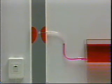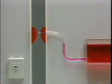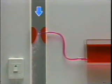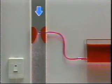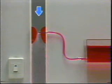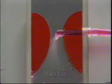Now, let's narrow down the mouth of the tube to speed up the airflow and see what happens when we try it again. As you can see, liquid is atomized, that is, changed into a mist that can be blown out through the pipe. This is basically how a carburetor works. The portion that was made narrower to speed up the airflow is called the venturi.